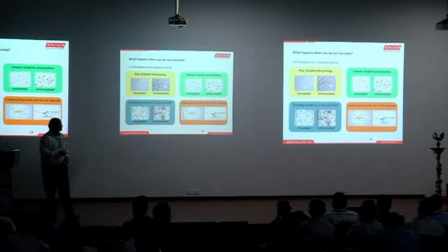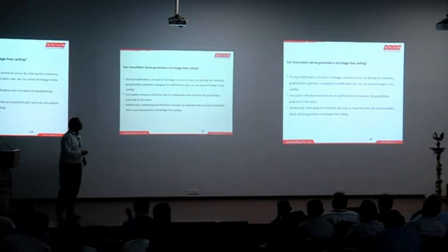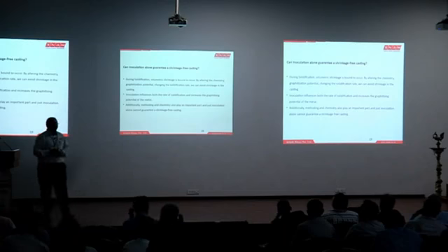And shrinkage tendency is not controlled. Sometimes this variation can come up if you do not inoculate. And undercooling. So all these parameters are related to one another. Again, can inoculation alone guarantee a shrinkage-free casting? No. Actually, inoculation is just a complement, or it is just an add-on we do.